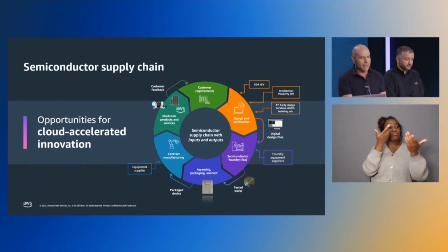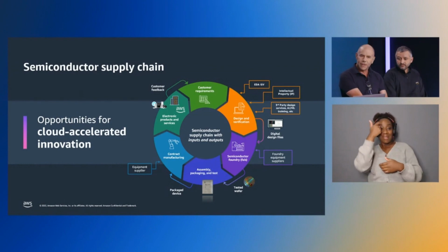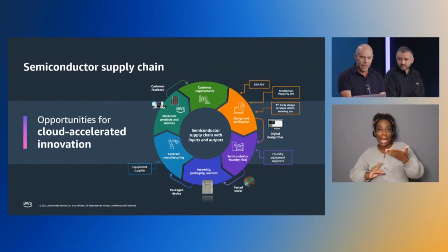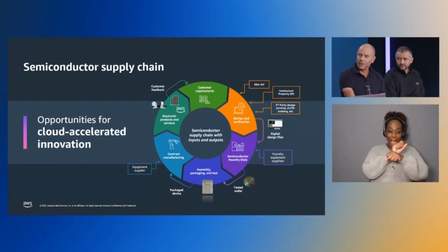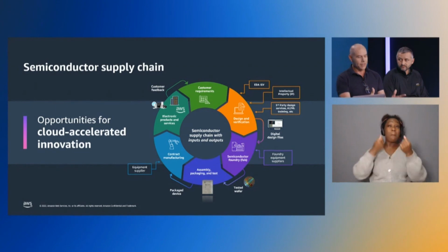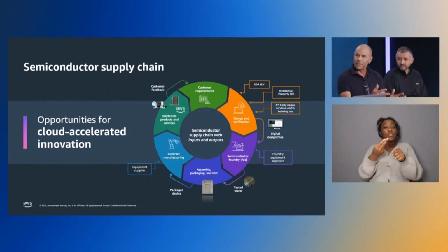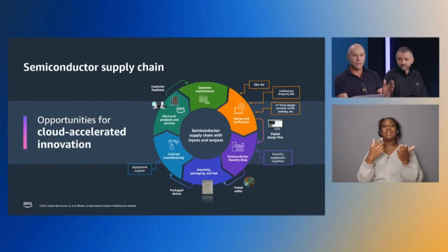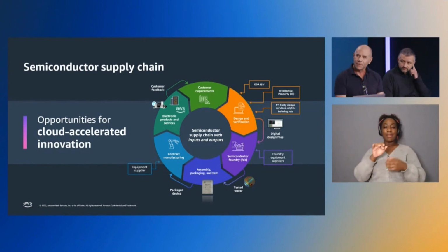For silicon design, though, the challenge is that going from a design language for hardware to actual working silicon that you can test can be a months-long process, or in some cases years long. And so you want to compress that as much as possible by using high-quality simulation tools, verification tools, logic synthesis, emulation, lots of different ways to pull that schedule forward. But at the end of the day, it's a hard problem.